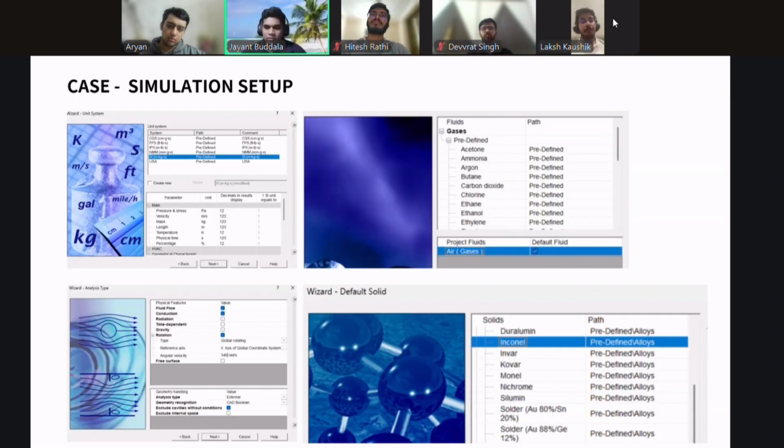For our case setup, we defined air as a working fluid and used realistic materials like titanium and Inconel, defining the materials of our components. We defined the different rotating regions for the different stages in a turbofan engine, like defining a rotating region for the fan, compressor, and the turbine with different respective RPMs, and set their inlet velocity and outlet pressure, and the turbulence model was selected.